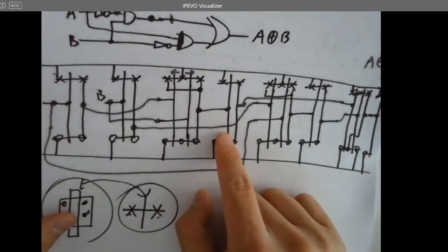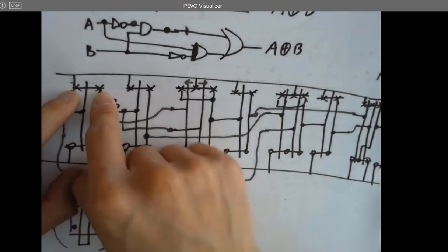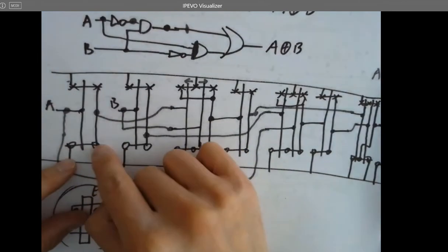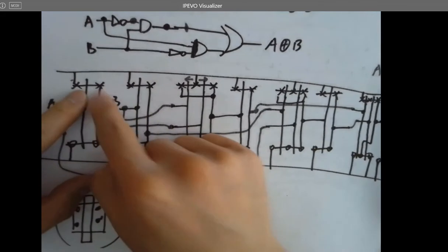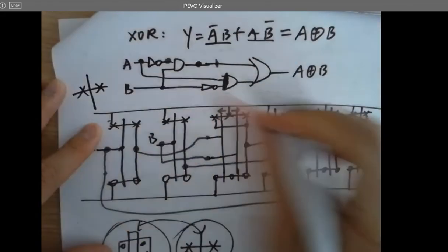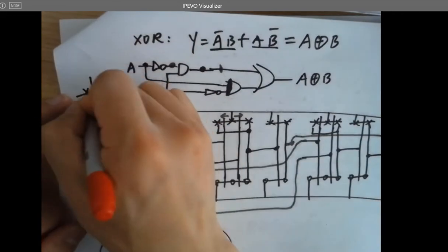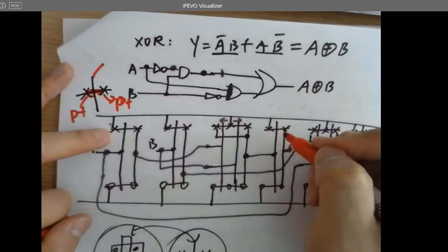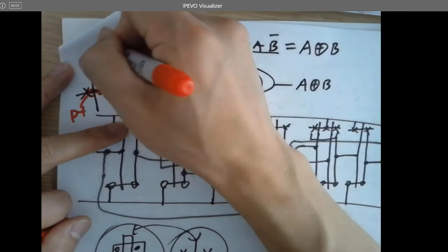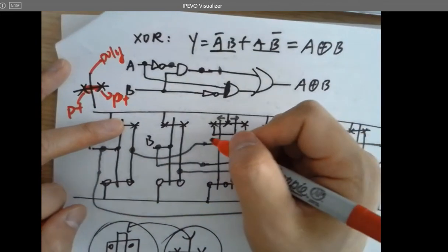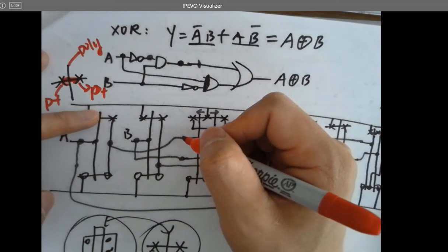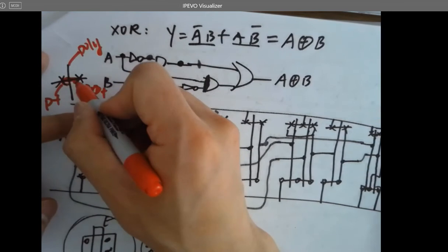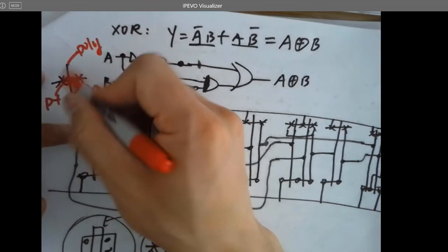Are you getting this? I mean, what are these two? What is this? There are two crosses, a little bar in the middle. What is this? That's a PMOS, that's NMOS. Where's the channel? Yeah, the bar between the channel, right? So here's the channel. That's a PMOS, so this is a P plus. Here's a P plus. What is this material? Polysilicon. What's the color in Electric VLSI? Pink. Yeah. That's a gate, right? And that's a channel. P plus. That's a PMOS.